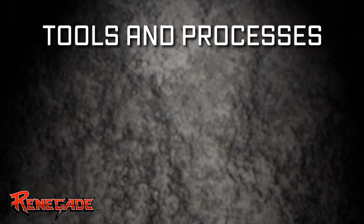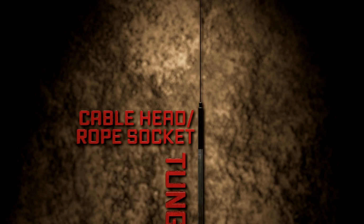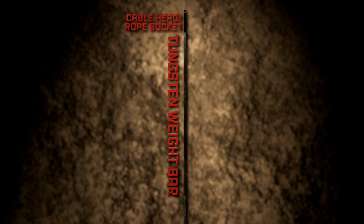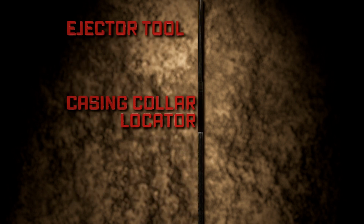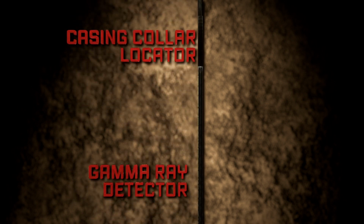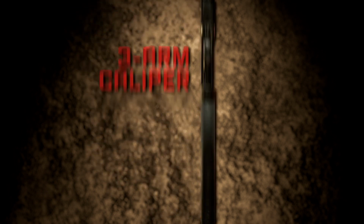Let's dive deep into a well and learn about the tools and the processes that Renegade uses to gather valuable data used to build an injection profile log. Working from top to bottom, we have a cable head rope socket and then a tungsten weight bar. Next, with the logging tools, we have our ejector tool, casing collar locator, gamma ray detector, 3-arm caliper, and temperature tool.